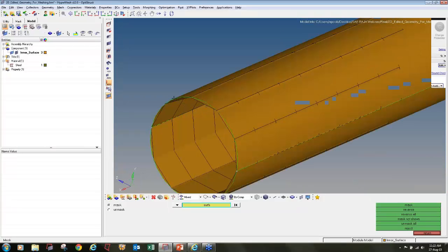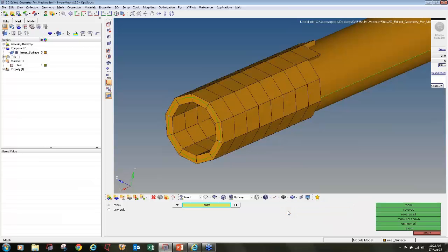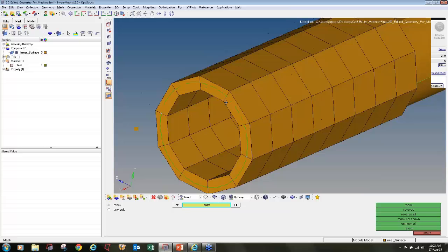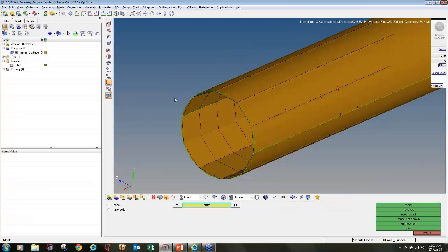As I already told you, the element should represent exactly how the geometry is representing. So if I make it in a 3D representation, you can see it has taken the thickness half up, half down. So it will become exactly as per my pipes. But if I had done 2D meshing on the surface, it would give me double the thickness, which is stiffer, which is not correct. That's why I want to do meshing on the mid surface and give the thickness, to divide my geometry properly in elements and nodes. So this is done now.